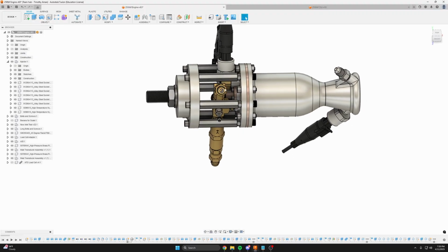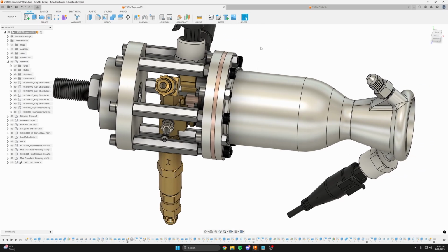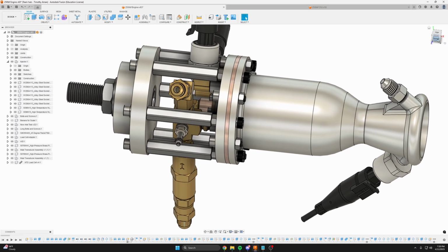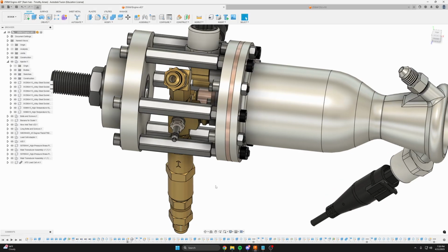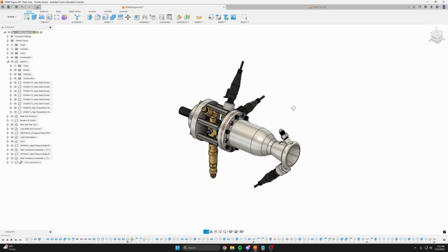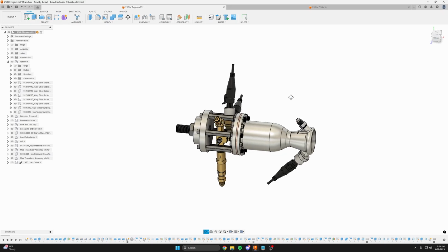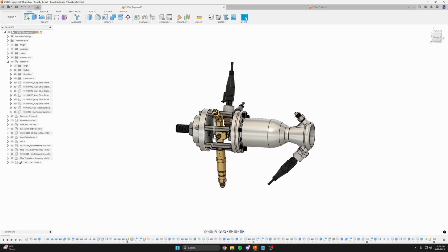For the fuel, we just used the same ethanol that we use for our main propellant as well. So the fuel is common, but the oxidizer is different, and you only really need a little bit for a few seconds, so it's not a ton of GOX to carry on a flight vehicle in the future. That's proven to work pretty well for us. It is probably possible to light a liquid augmented spark igniter, but we have not been able to demonstrate that, so we'll leave that as an exercise to the reader.